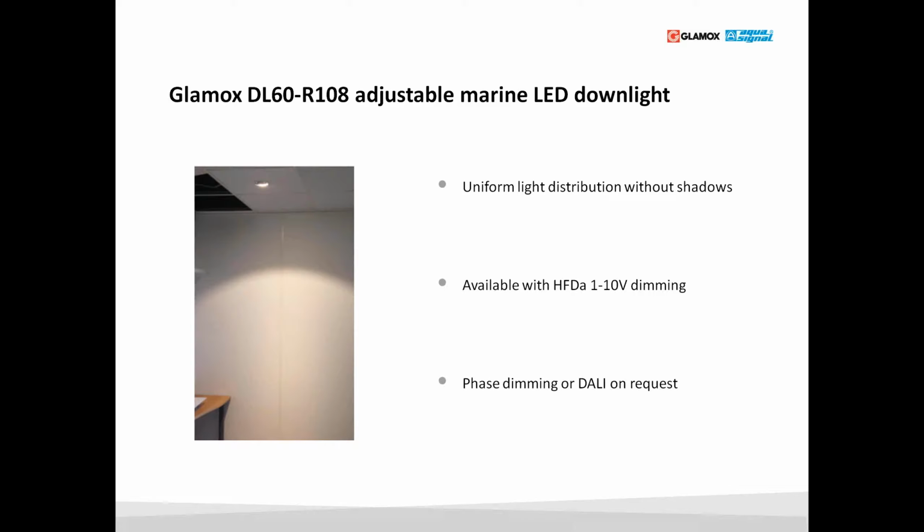Of course, that is a limitation against the old dimming systems and the new LED drivers and how they are working together. It's not an easy fix to have a phase cut dimming retrofit. That's an issue we are working very hard to find a solution on, but we don't have it yet. On a new installation, phase cut dimming is not the problem. It's on the retrofit that we have a challenge, but everyone has a challenge there. No one has a fitting that works with the old phase cut dimming systems they had about 15 years ago.